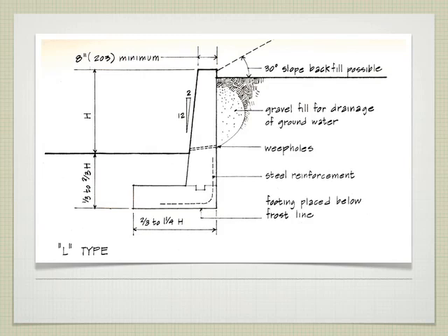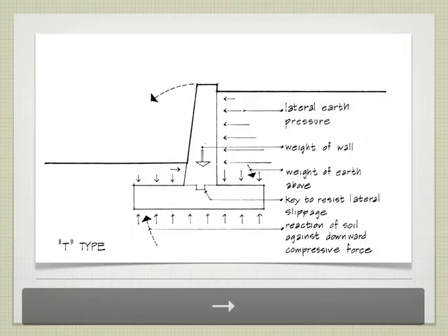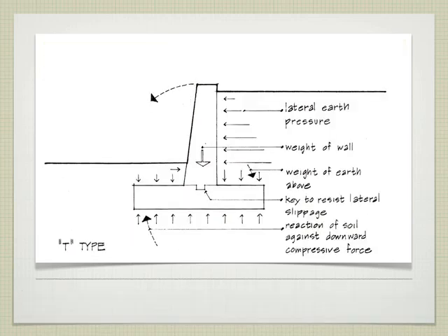In this particular example, we have a tapered retaining wall, which helps. We have a nice footing at the bottom. Remember when we talked about footing, that when you load this, it wants to overturn that way? Remember that when we talked about that on a footing? In this case, it's a good thing, because we've got a bunch of stuff pushing it back that way. A bunch of weight from the hill pushing it back that way. So we get the benefit of the fact that it wants to overturn, helping us to hold the hill back.